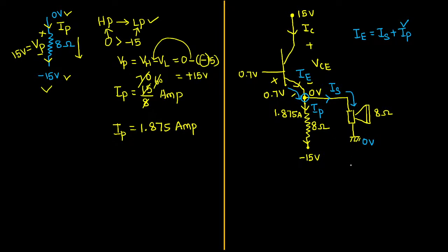For that, I'm taking the speaker and drawing its equivalent circuit. They had given only one data about the speaker, that the internal resistance of the speaker is 8 ohm. So electrically I'm replacing it by its corresponding resistor, because I just wanted to know the current flow. On the top, what is the voltage here? Can you please tell me? This is 0, sir. See, they only told. We have identified this voltage. If here it is 0, then here also it is 0 only. So on the top of the speaker, we have 0. The bottom is connected to the ground, so that is also carrying 0.